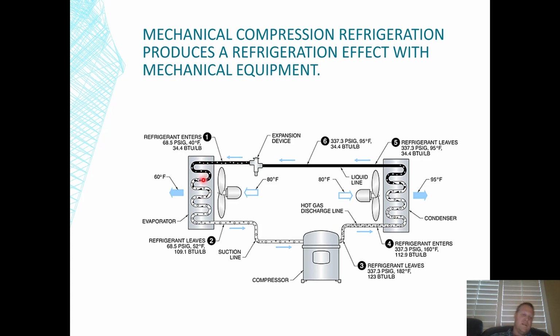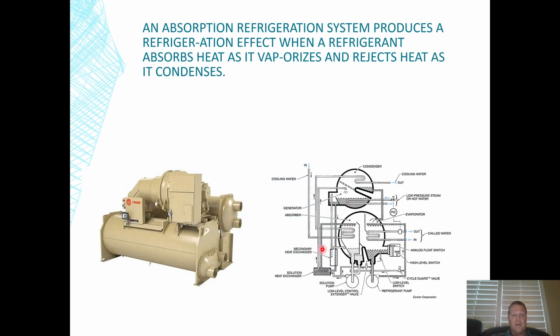We're taking compressed liquid refrigerant, moving it under low pressure, and letting it expand into a gas, and it steals all the heat out of the air. Well, that's really what's going on in a chiller as well, but instead of cooling air and heating air, it's cooling water called chill water, and it's heating water called cooling water. Chill water, cooling water.